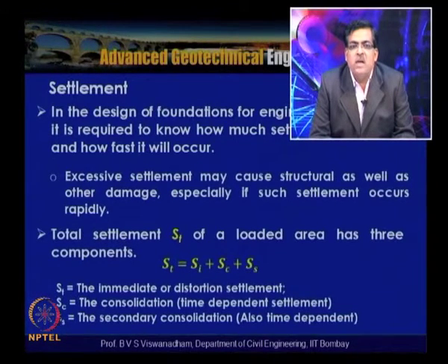But this occurs at the end of the process of consolidation under the constant effective stress. That is nothing but the creeping of soil particles, and the void ratio will continue to change under the constant effective stress.